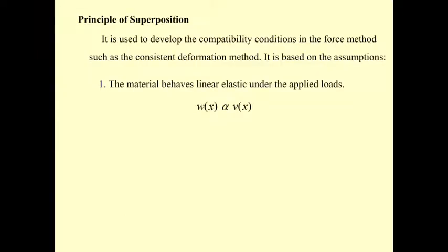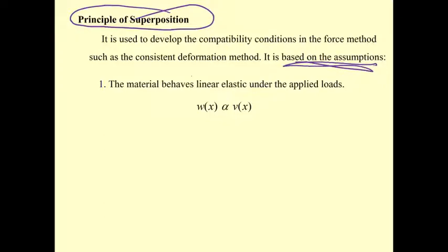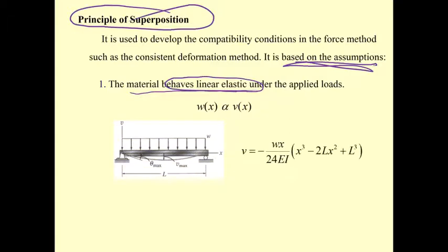Okay, and anyway, whether you use the force method or the displacement method, you are required to use the principle of superposition to separate the structure into many cases. It's up to the problem you are considering. Okay, and this principle of superposition is based on two assumptions. First, under the force, the material behaves linear elastic. Okay, and this follows what we studied.